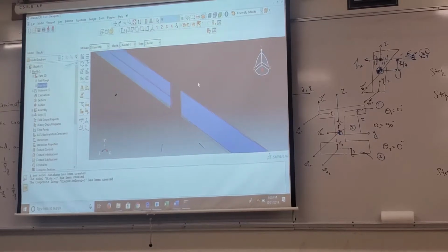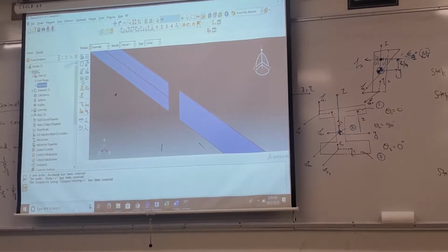And what we have to do is bond these such that they are like a T-section. So now I use this create constraints. I will create a constraint which is face to face. I will use the face of this web with this flange partition, and it gives me the arrow. I will flip the arrow so that they point in the same direction and press OK. Enter 0 value, and you see the orientation has changed now for the web.